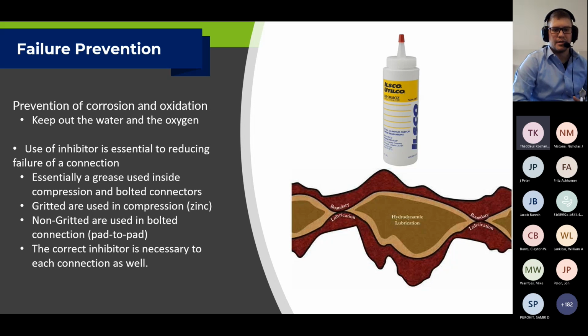Very interesting. How are any of these considerations affected by high voltage DC, as opposed to traditional high voltage or extra high voltage AC? That is a good question. My experience is more on the high voltage AC side, so I don't want to lead you astray. But certainly the corona issue is different, obviously, with high voltage DC. But all the other ones would seem probably not so different, except maybe some of the corrosion issues. Yes, and that is one I always like to say: always remember one thing, keep your aluminum above your copper.